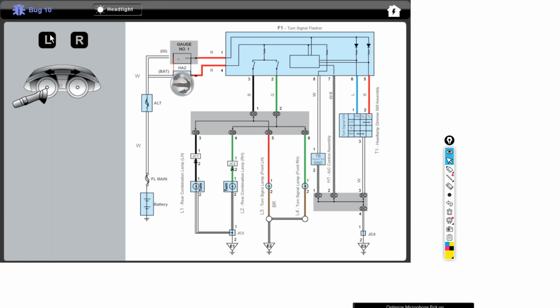At this point, you can see the headlights blinking dim. Also, the left side of the lights are blinking dim because we've created a series parallel circuit. And this is what's so great about that circuit, especially on a bulb circuit or something like that. You would start unplugging connectors, you got a bright bulb, and all of a sudden the bulb goes dim and the bulb at the front comes on. The one on the front's out, you know the short's somewhere up front.